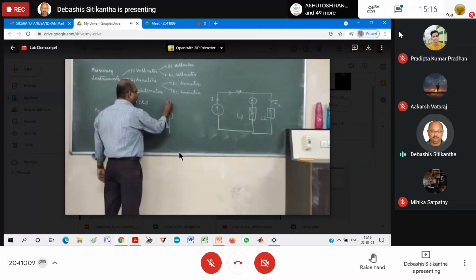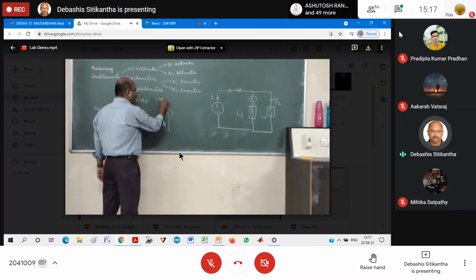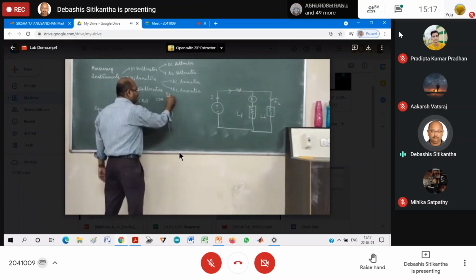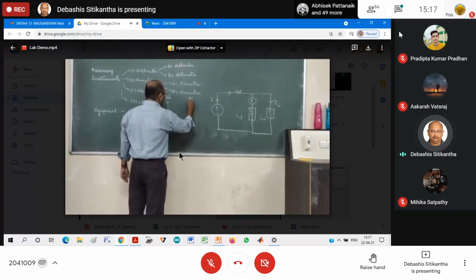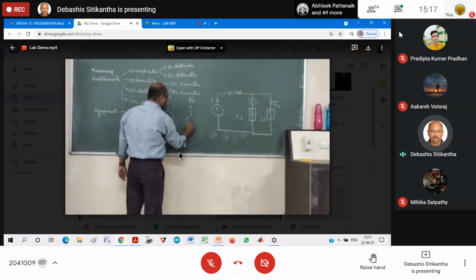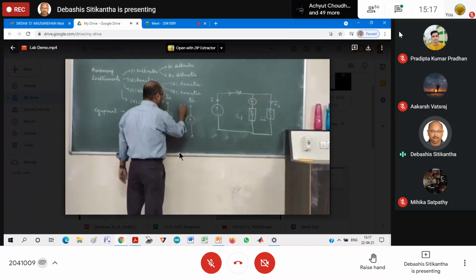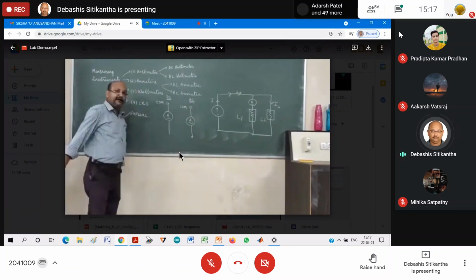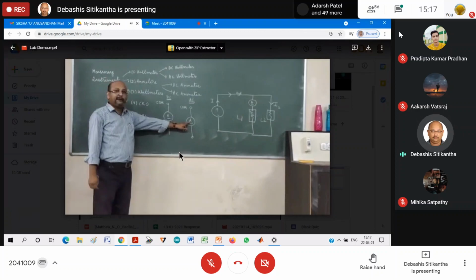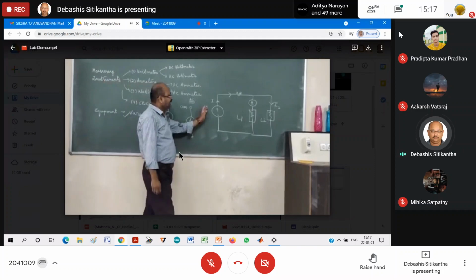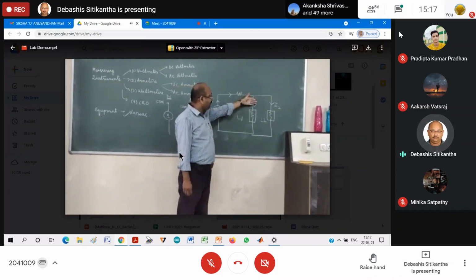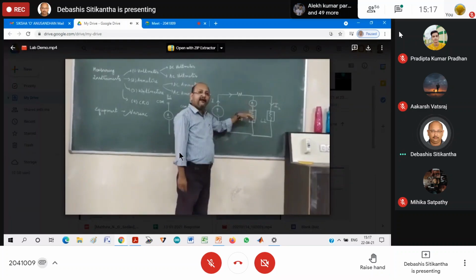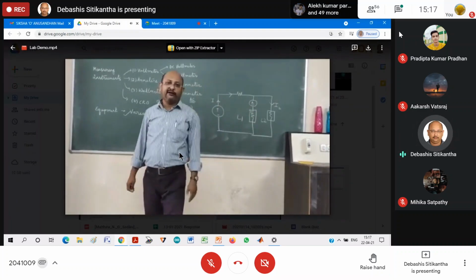Again, here you will have a terminal which is named COM. So this is your DC ammeter, and your AC ammeter will have a symbol like this, similar to that of the voltmeter, except the letter is replaced by the capital letter A. Exactly in this manner we are going to connect it in series, and this ammeter is going to give the reading. The same procedures are going to be followed over here.